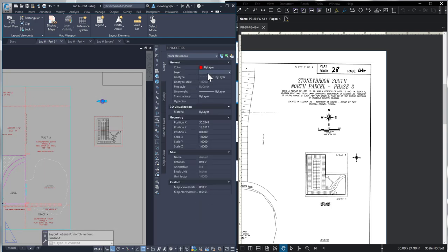It also puts it on, I'm not sure. I'm going to do 0 and put it on the boundary. You can put it on a north arrow boundary. The nice thing is this arrow follows whatever rotation the view actually is in. I'm going to make this a little bit bigger, so I'm going to scale that up to 2. That's not what I wanted to do. All right, maybe 2.5. All right, so there's your scale.